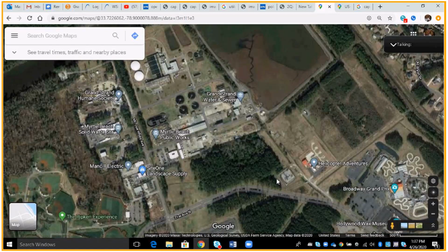Substation, fixed bank, close to the load as I could get it right here. The reason why this is a wood pole and these are steel, I couldn't mount it on a steel pole. And there I have my 3-phase inductive load that stays on all the time. So I went ahead and put a bank in there. Not I, but an engineer requested a bank be put in here that stayed on 24 hours a day, 7 days a week, 365 days a year.